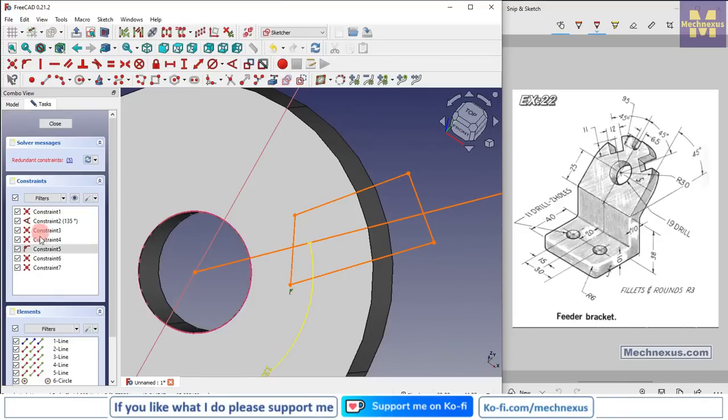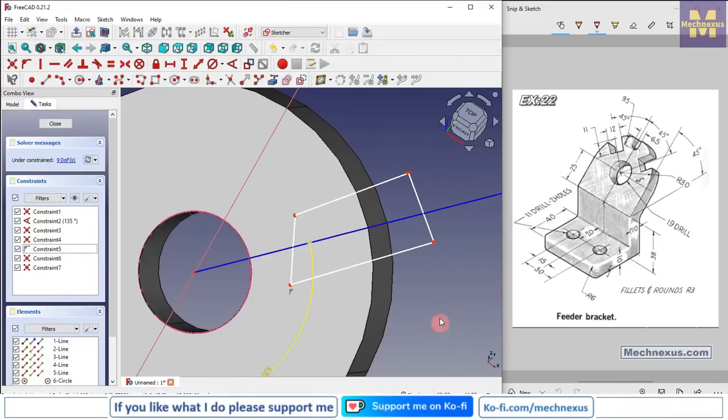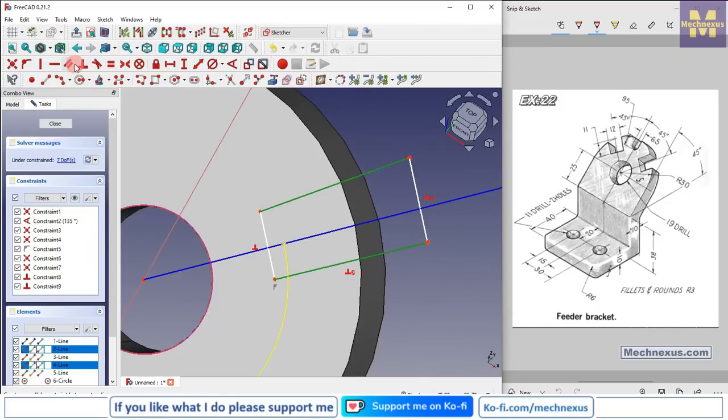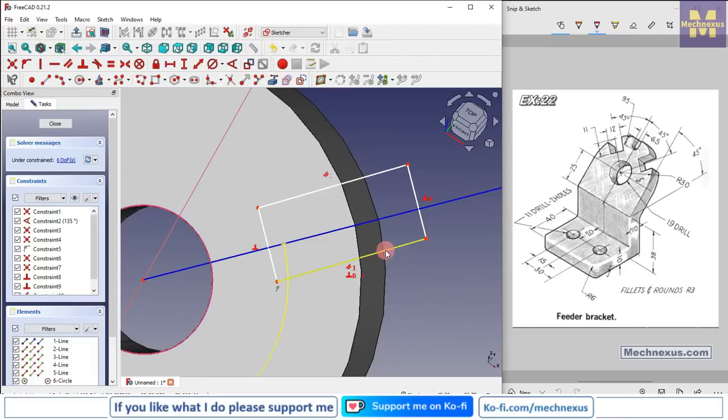And now we will deactivate the conflict constraint. Now here we will select this and this and add a perpendicularity, this and this and add a perpendicularity, select this and this and add a parallel relation. Now select this and this and add a parallel relation.